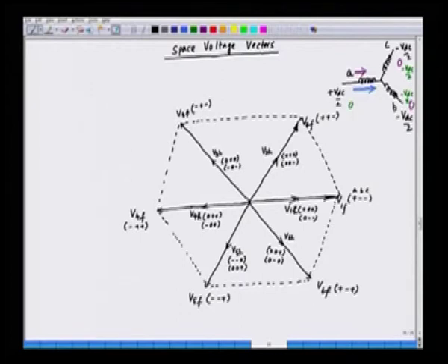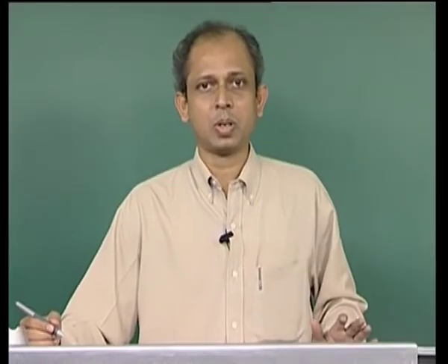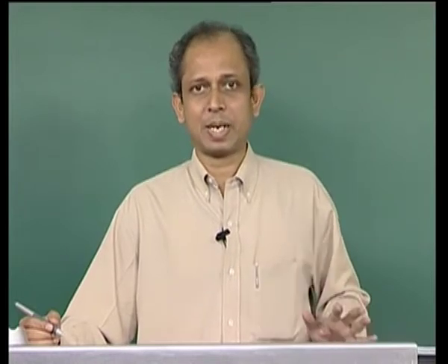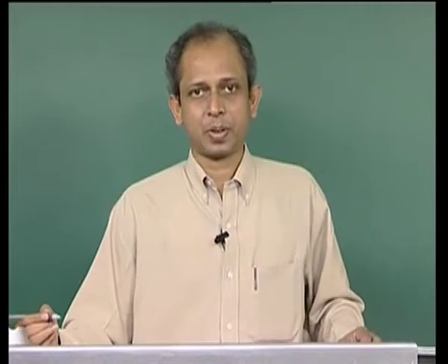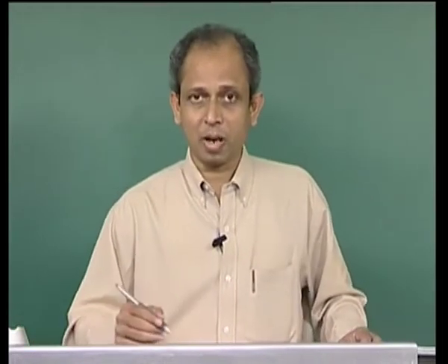So, do we have any other voltage vectors? Because we have to find all possible combinations which are relevant here. Now, we have intermediate voltage vectors. It means in between V1F and V2F we have one V1I, and that is called an intermediate voltage vector. So, that is shown in the following fashion.